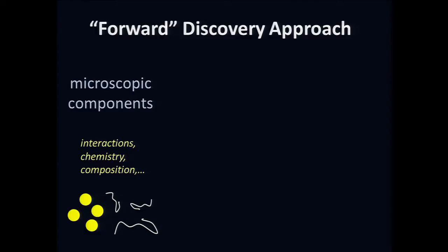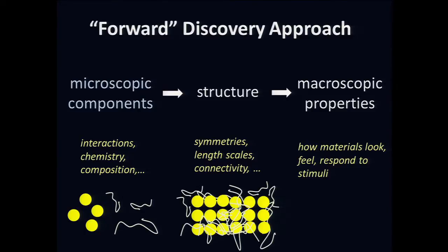If you think about this in a really naive sense, if you want to create an entirely new material with novel properties, one way you could go about it is just try to select two or more components and mix them together. And these components may individually exhibit some of those properties you'd like to see in the final material. And if you do that, inevitably what you see is that structural order emerges. And this happens actually automatically. It's not something that you have to turn on. Now, it may not be the structure that you like. It might not be the structure that you envisioned. But ultimately, structural order has to emerge because of the interactions between the components and the material. It can't be turned off. So perfect randomness is never an option in condensed phases. This is a basic rule of statistical mechanics.